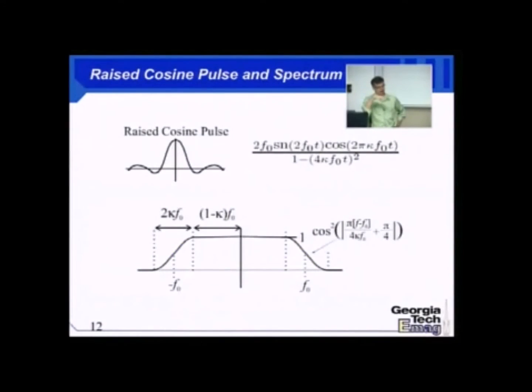All those pulses are going to blend together, except at these very discrete points where I want to estimate the amplitude of that pulse. I now need to run this signal through hardware or some sort of equivalent signal processing in software, a device that pulls out the best, cleanest estimate of that pulse amplitude. What is that device called?